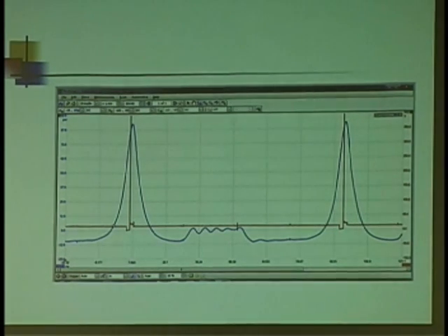And then we get back to TDC. Now, just like I showed you with the starter, I can use this as a gauge of timing, because is that crank position going to change? Is everything referenced to where the piston is? And that's not going to change. Everything else might, right? The cam sync can change.